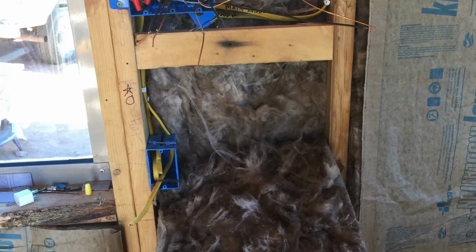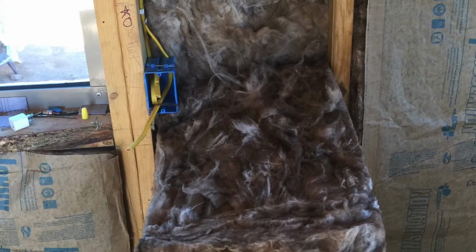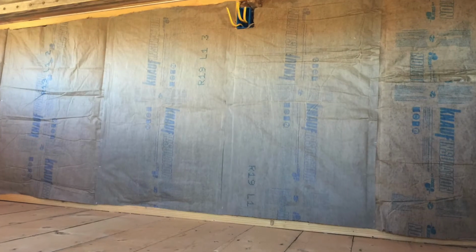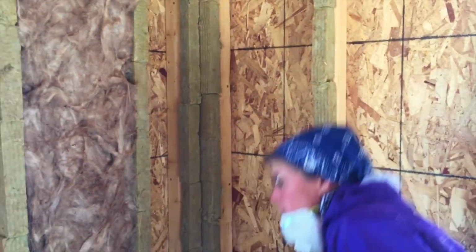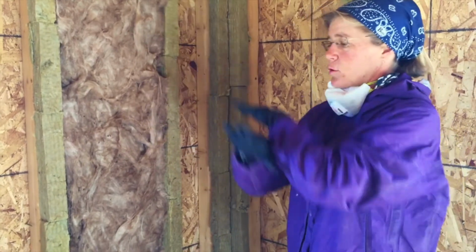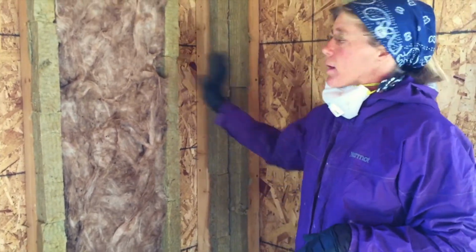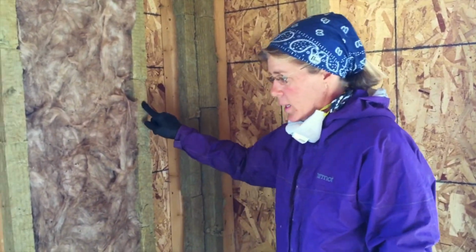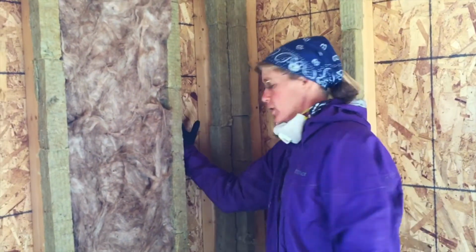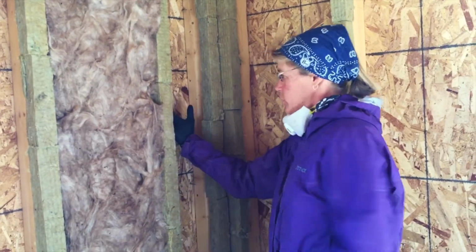Fiberglass insulation is the most common in our area. Some things you want to know about fiberglass insulation is 1, it's itchy as all get out, so don't handle it without gearing up. 2, it comes in different thicknesses depending on the depth of your walls or ceiling. So really trying to plan what type of insulation you're going to use before you build will help you determine what you might need in your ceiling and in your walls. And then also what additives are in it. Some insulation definitely is a little bit less toxic than others. So do your research on your type of insulation and what's available for you.